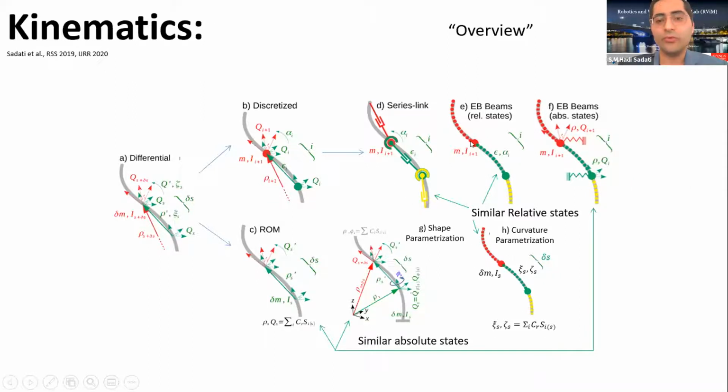You use it with relative states. The advantage of using relative states is it usually matches your actuator space, and you end up with the minimum number of coordinates, basically the generalized coordinates, as Federico mentioned. But the equations tend to become very complex and lengthy.